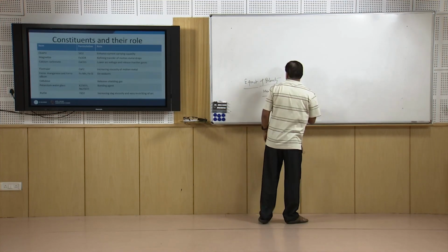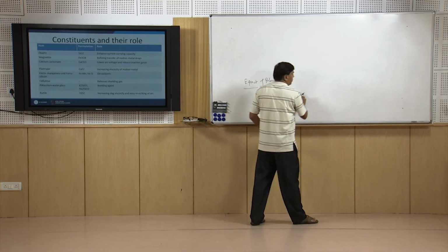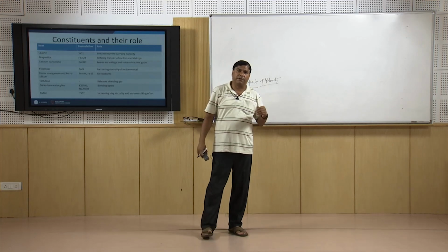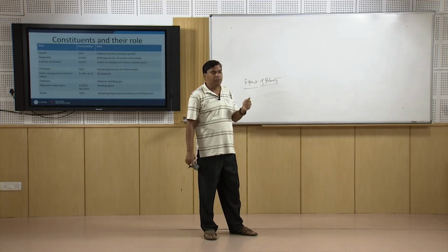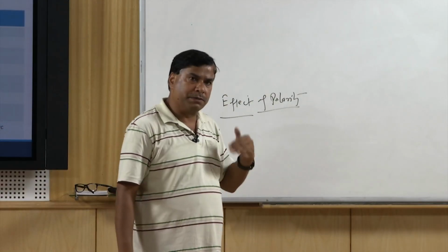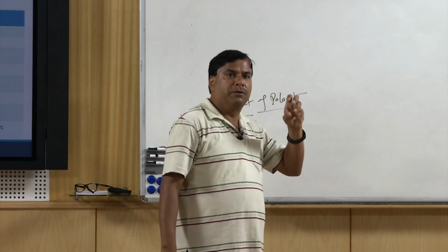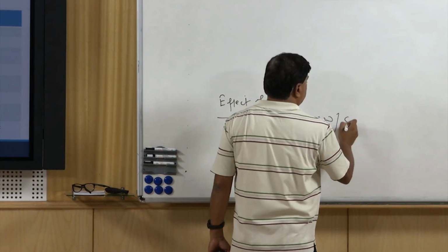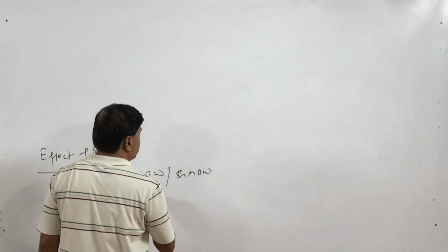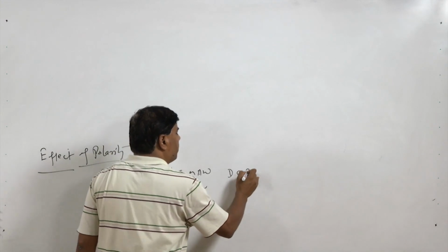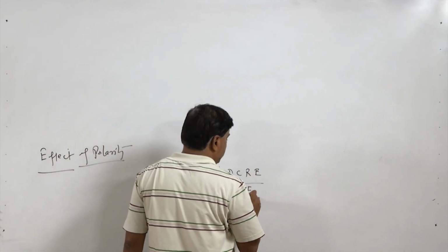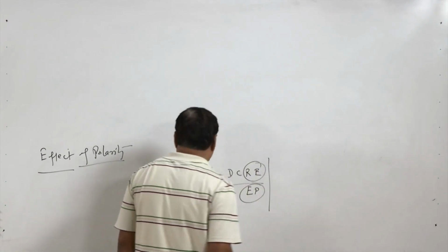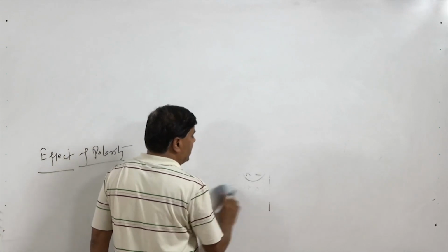While in other processes like submerged arc welding process, if you want higher deposition rate, so in that case for submerged arc welding process we want that more heat is generated in the electrode side, and for that purpose we will be using the reverse polarity where electrode will be connected to the positive terminal and workpiece will be connected to the negative terminal. So, the higher amount of the heat generation in the electrode side will be leading to the higher melting rate. So, invariably in SAW and for the GMAW gas metal arc welding process, DCRP or DCEP, like electrode positive or the reverse polarity, both are same, and this kind of polarity is used to have the advantage of the higher melting rate.